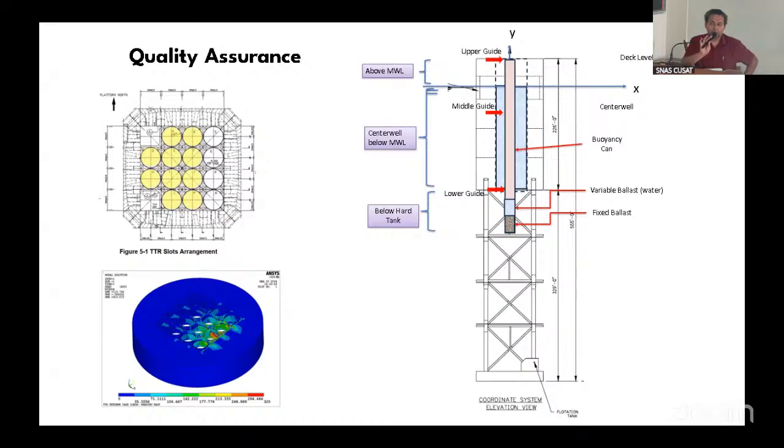You need to do a QA for any FE analysis. The idea is, however complex your model is, try to reduce it to something that has a closed-form solution. You are not looking for an exact answer, obviously. You're looking for what's known as a ballpark, an approximate number. So if you have a complex problem like this, and your beam model is within 20 to 30%, then that's good. If it is 2 times, well, maybe that is also fine, because maybe you are not capturing all the effects in your beam model, but I would advise you to check the model. If it's 10 times, you're way out wrong.